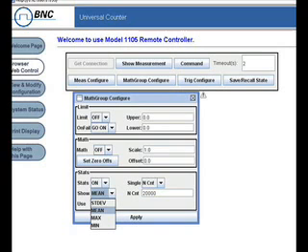Gate and external arm. There are 4 arming modes: auto, time, digits, and external. In external, a signal on the rear panel determines the window with which measurements are taken. Trigger config allows you to turn on auto triggering.